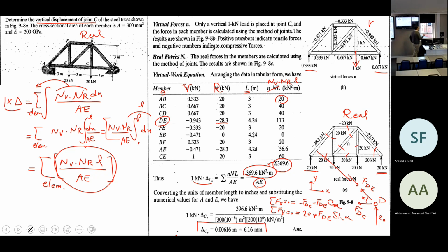Anyway, you can stay with this and minus 28, or you can put it in this direction and make it positive 28. Okay, but we don't really do that. We stick with minus 28 all the time for forces in compression, in tension. Any other question?